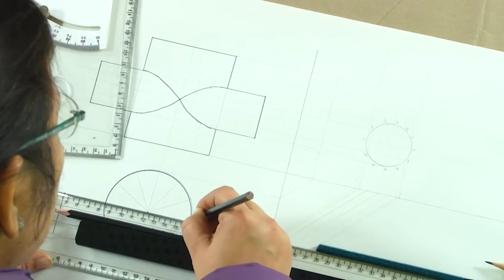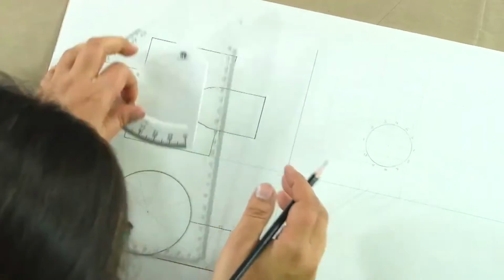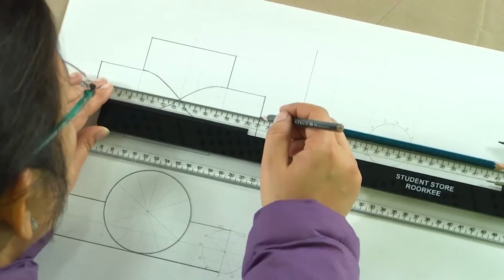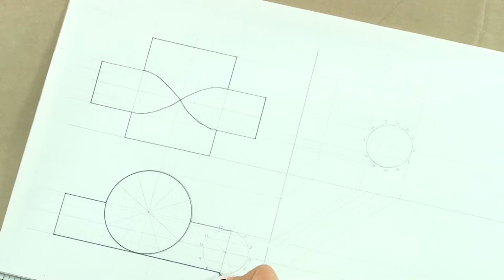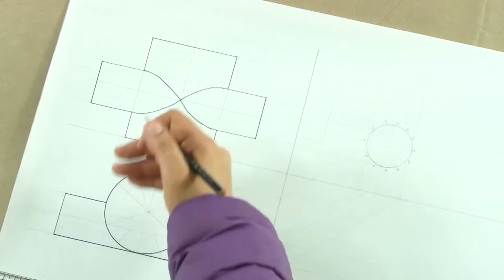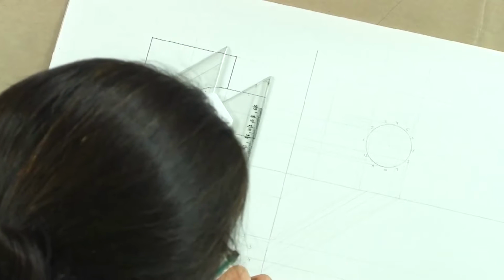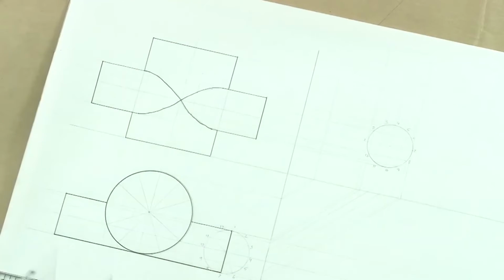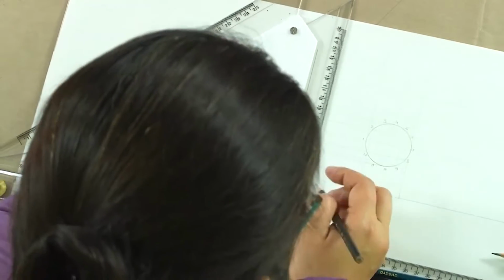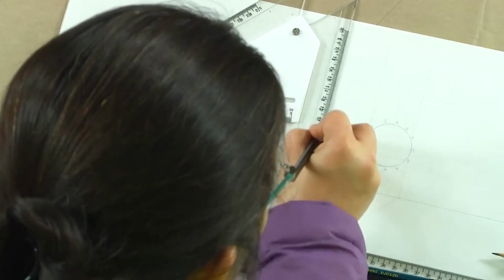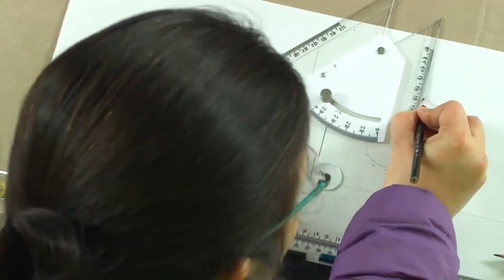One of the edges of the smaller cylinder, the horizontal one, will be seen continuous, which is what we are seeing here. So this one line, this one generator, which is 1 and 7, which is this 7. So, here it is only the 7, 1 is going inside, it is passing through like this. This is what you will see from the top, this is what you are going to see from the front, and from the side we will be seeing the most clearer of the pictures for this particular combination.